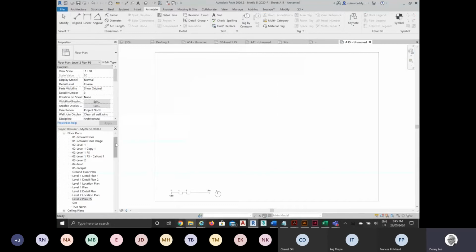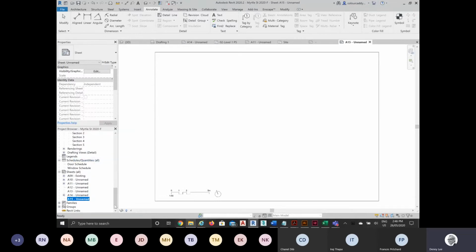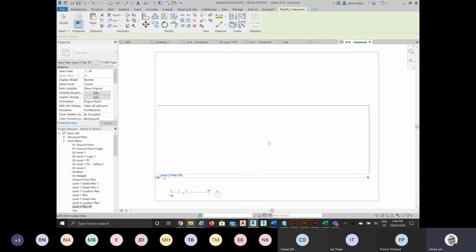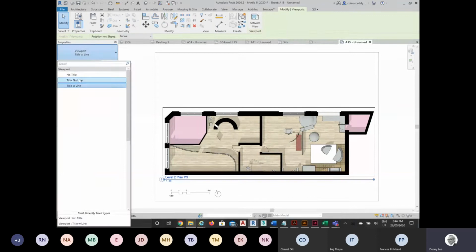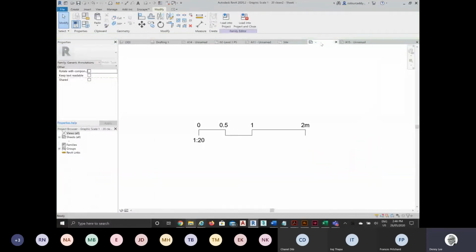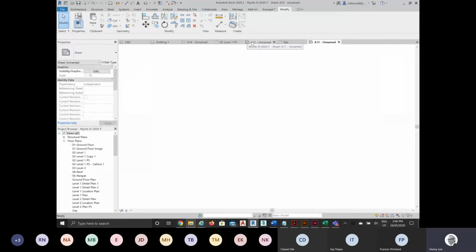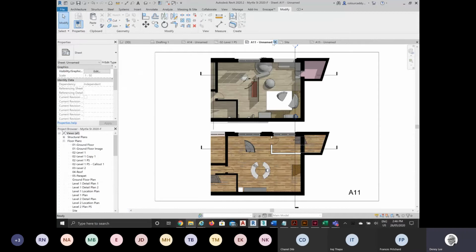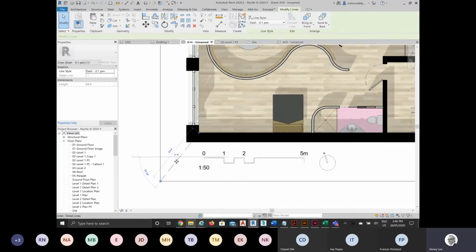And it is already on another sheet, so I'm just going to delete that sheet. Here we go. Okay, so I've deleted the sheet that the plan is on, so now I can put the plan onto this sheet. Now to get it in the right spot, I'll go to, oops, I've got a few things open. Just go back to the one that had the, not that one. So this is why you want to keep closing your tabs. There we go. So this is the one that has the plan with my detail line that I've drawn.